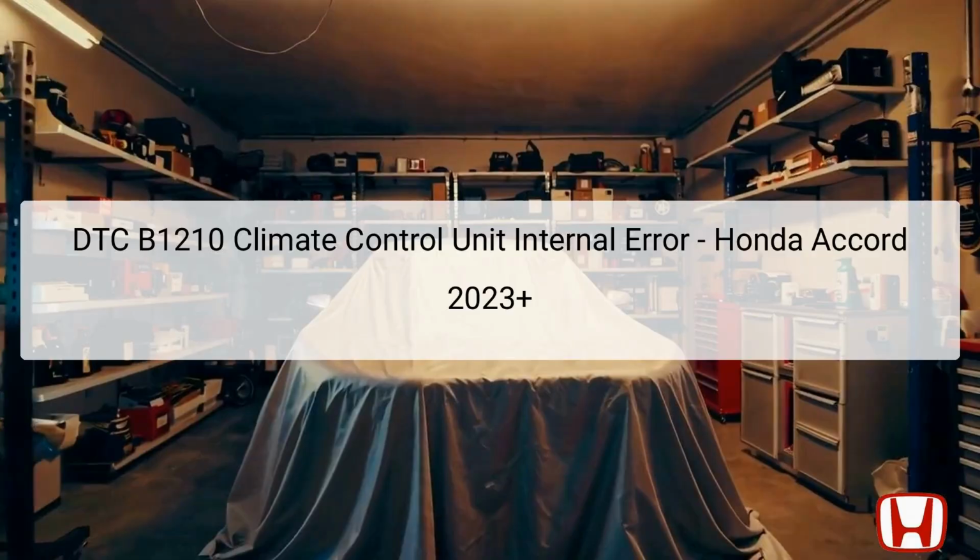In this presentation, we will analyze DTC B1210, which corresponds to a climate control unit internal error in the Honda Accord manufactured in 2023 and later. This error indicates that the climate control unit, a critical component responsible for regulating the vehicle's heating and cooling systems, has detected a failure in its internal electronic control unit, ECU. The ECU is crucial as it processes input from various sensors and data to control climate settings effectively.